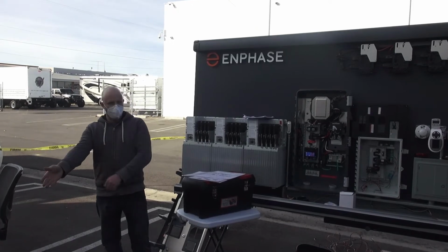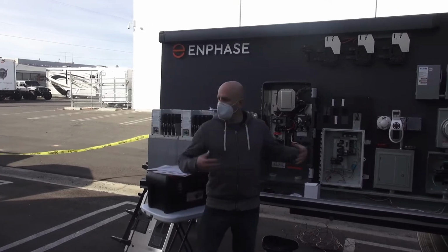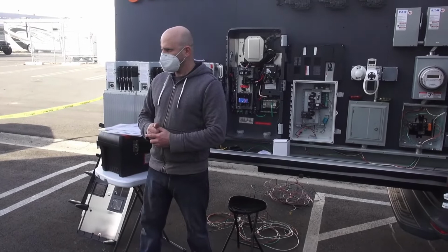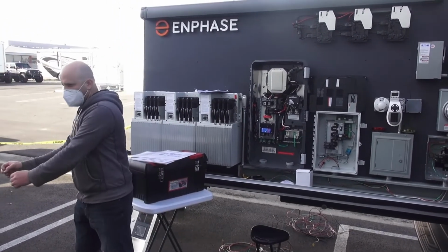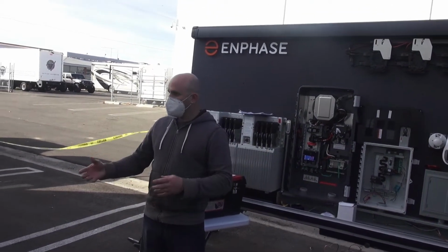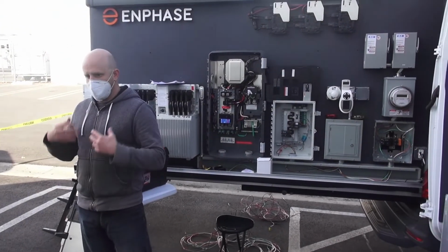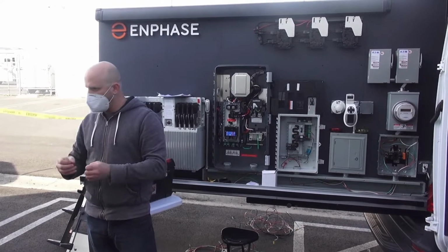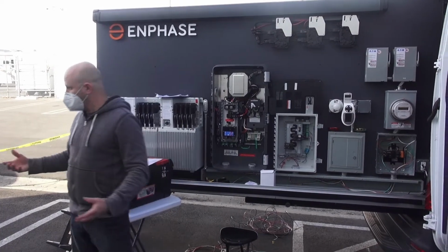There it is. So this guy, you guys follow him. He knows his stuff, okay? The consumption CTs, what do they need to measure? Because we have to know how much power we are using. And where do you install them specifically? Do they need to measure just the hot tub? Do they measure everything? So it's basically the main panel hot conductor. And when you say main panel, what I'm getting at is I want to measure everything, before the main breaker, after the main breaker, fine. But I'm trying to measure all of the energy usage in the house.